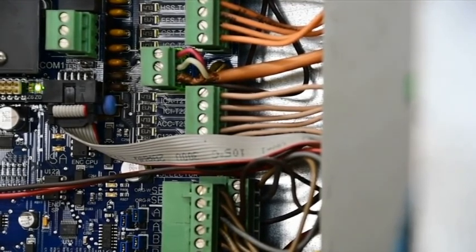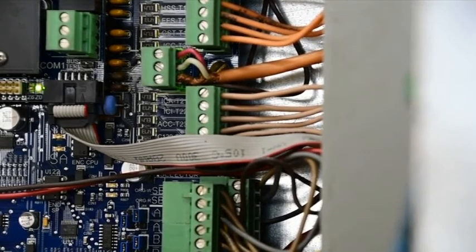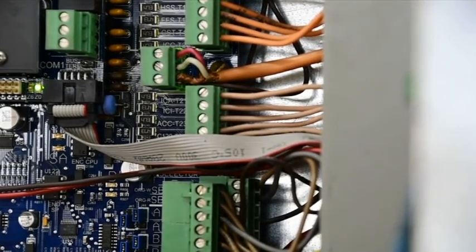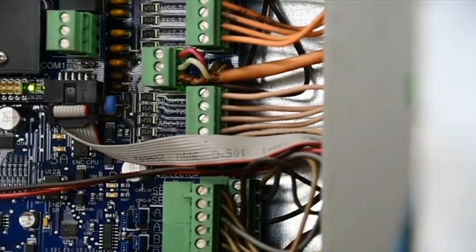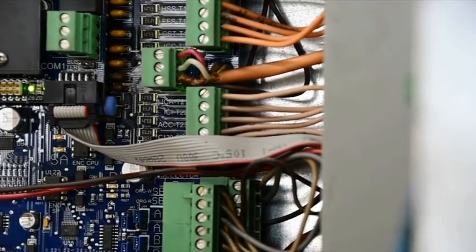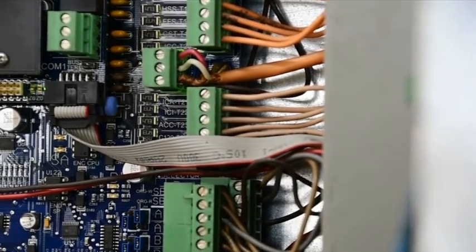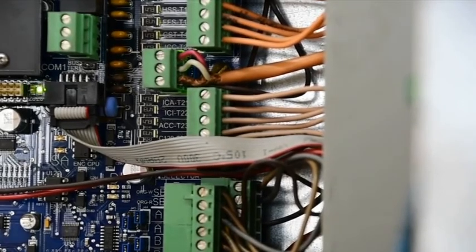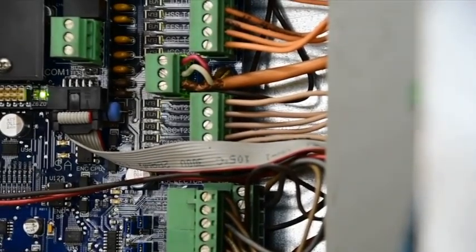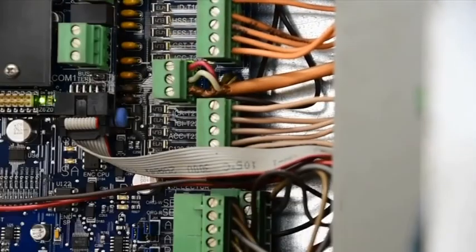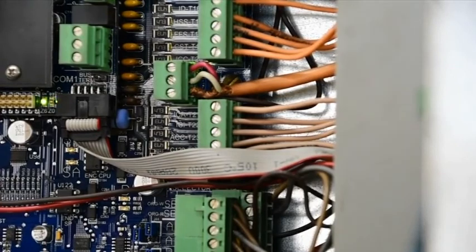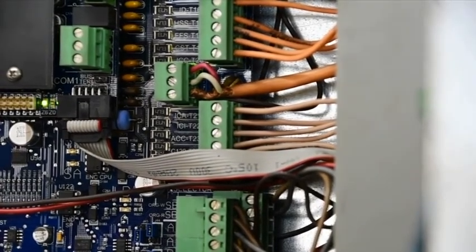With none of the inputs on, we have 3 systems that are monitoring it. One is the safety PAL, one is the safety processor, and one is the main processor. And we'll go through to show that each one of those processors will shut down the car and recognize that this is a fault. Okay, so we're going to reach up here, ICA, and we're going to carefully remove this wire. Now remember, it's got 110 volts on it, so care needs to be taken that it doesn't touch anything and that you are protected.